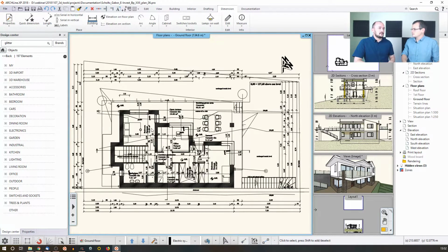The DWG file is not bad, but it's not the best because it contains only 2D. It literally contains lines, and sometimes it contains 3D objects, but it's not as complex as a beam object. It's not a wall. It's not a roof. It's just an object or a 2D drawing. So for that, I could use an IFC, which we always suggest users to use if you would like to communicate. If you do have the luck to communicate with other users using other BIM software, this is the most effective way, if you don't want to talk in documentation way.